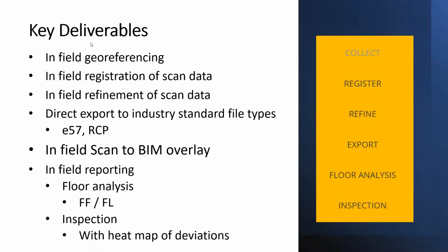And I will say the old way of scanning, having to put up spheres and checkerboard targets, scan against those, and hopefully you got everything right, and then bring that scan data back into the office and start your registration process was time consuming and extremely frustrating when you couldn't get it to register correctly, because you've left the field.